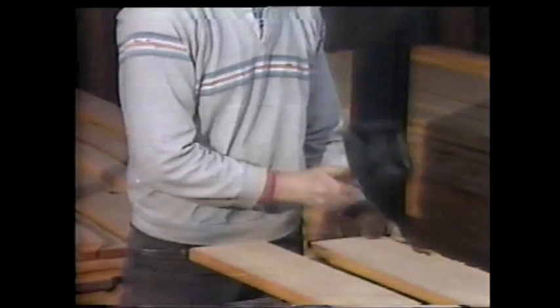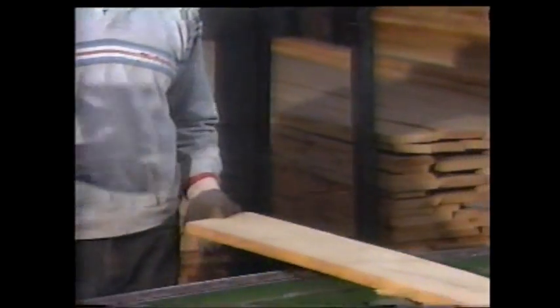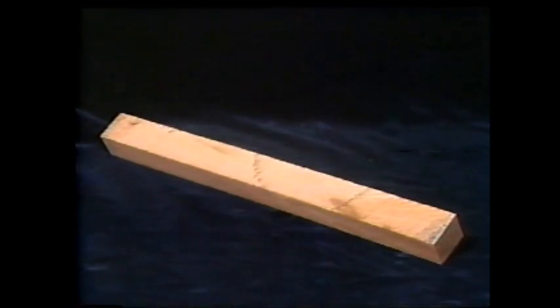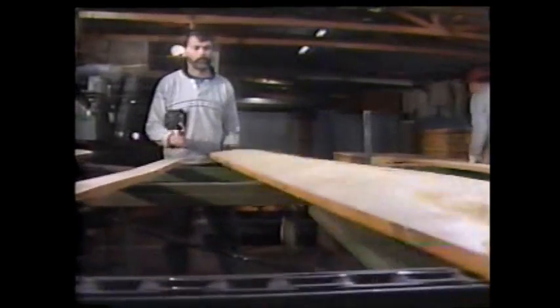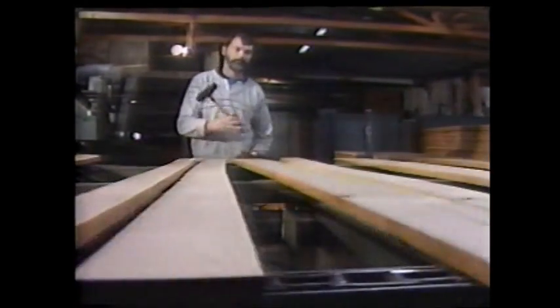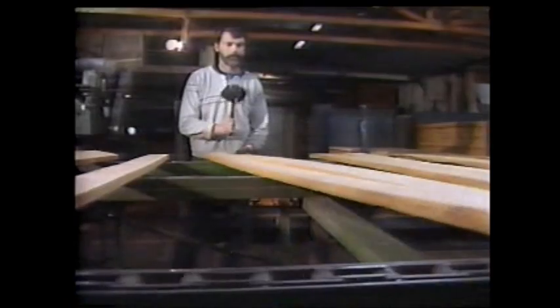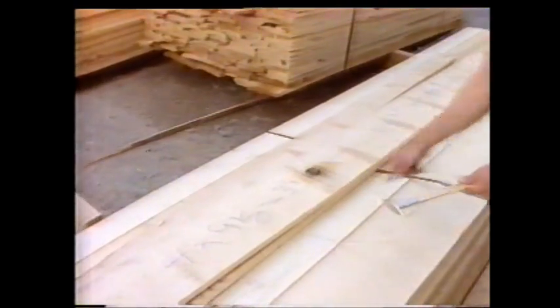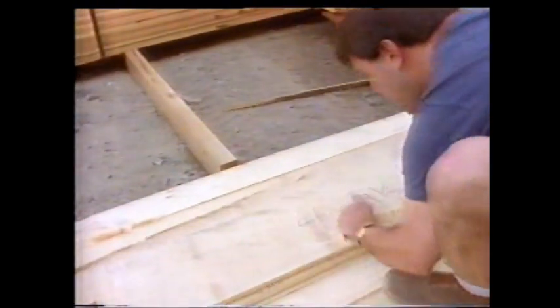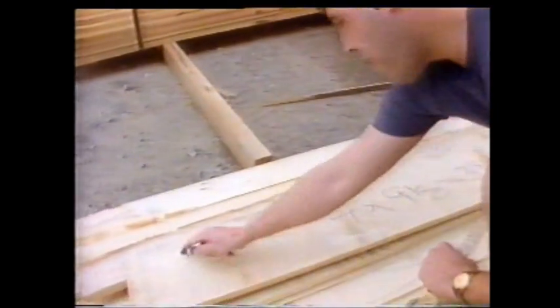If a board does not yield sufficient clear face cuttings units of the right size and number of cuttings, the inspector tries the next lower grade. A cutting unit is 1 inch wide by 1 foot long. A cutting must be obtained by cross-cutting, ripping, or both. It cannot be obtained by diagonal cutting the board. This board contains 70 cutting units and the minimum size of clear face cuttings to give it a grade of 1 common.